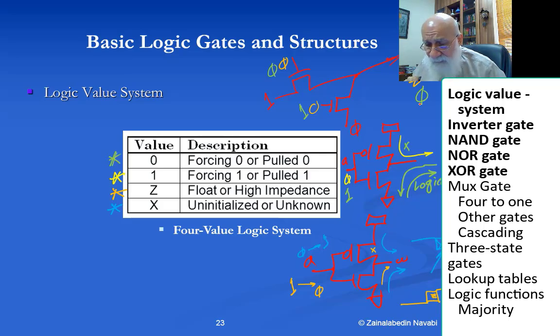All right, let's look at this situation now, where I have a 1 here and a 0 here. The lower transistor will not be conducting, and therefore nothing will be here, but the upper transistor will be conducting, pushing a 1 into this, and therefore my output becomes a 1.